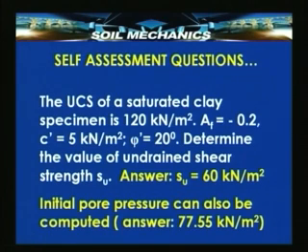Now, the other data that is given in this particular problem is useful for determining the initial pore pressure, and you can determine this in a manner similar to the recent problem which we saw in this lecture, that is the problem number 17. Using the similar expression, you can find out that the initial pore pressure is 77.55 kilonewton per meter square in this particular case.